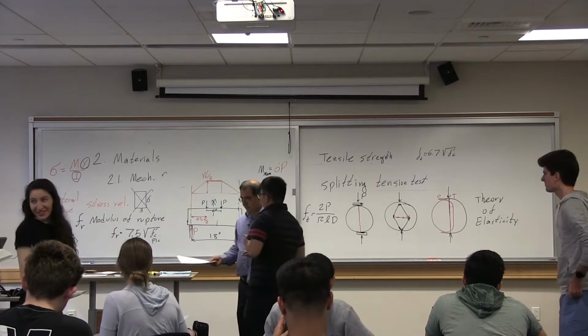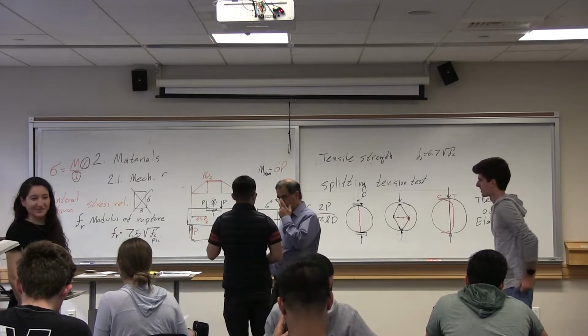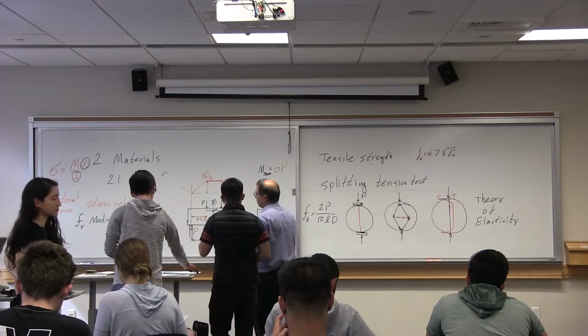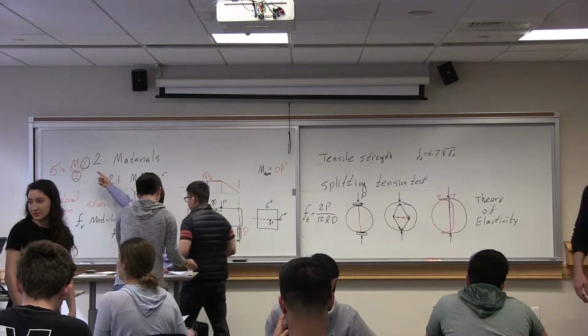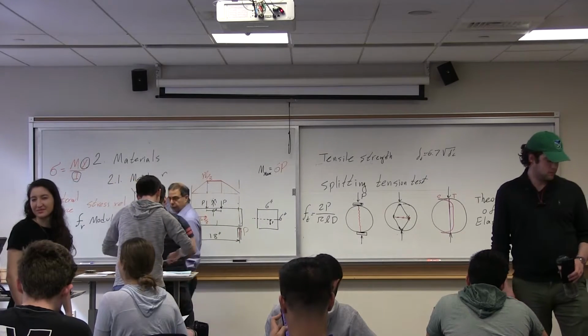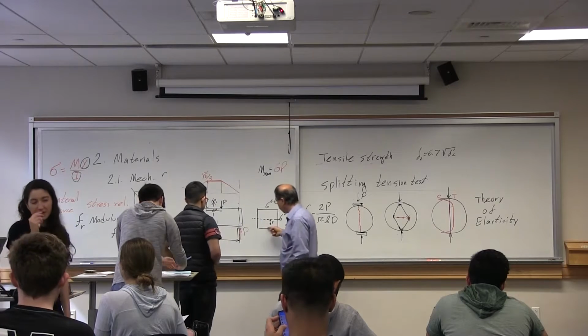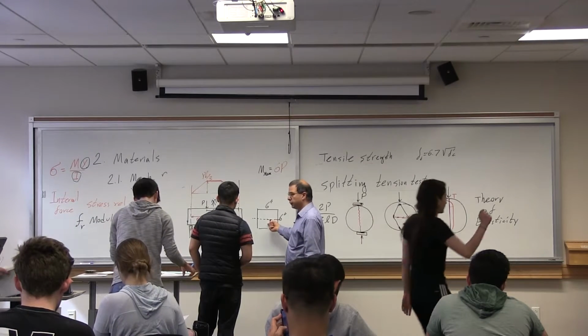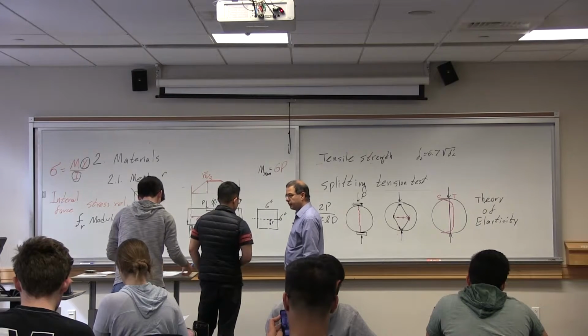For the bending, the stress is different at different points of the beam, right? Like at the bottom is the most. Yeah, wherever you calculate y from, that would give you the stress. If you use the y for this point, that gives you the stress here. If you use y for this point, that would give you the stress there. Okay.